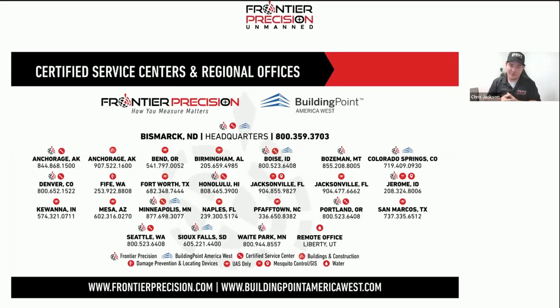So if we're wanting to create an orthomosaic, say from the camera module that's on the Voyager, we have to plan our flights for spacing that represents our photogrammetric product that we want to produce. And then thankfully we have the tool in Cloud Station where we can cut out all those duplicate points because we're going to have a much higher overlap for the LiDAR than what we typically would need.